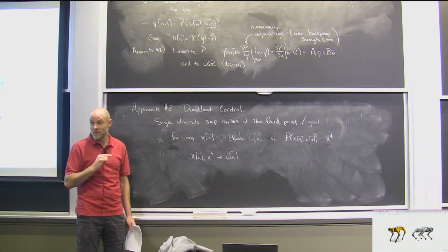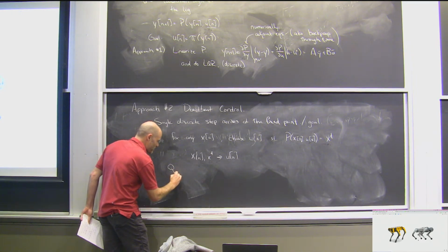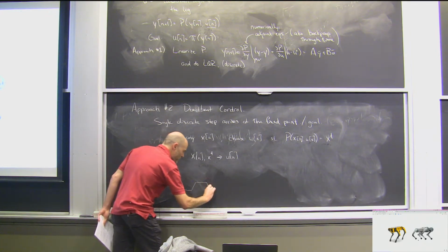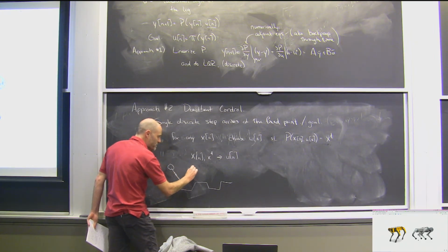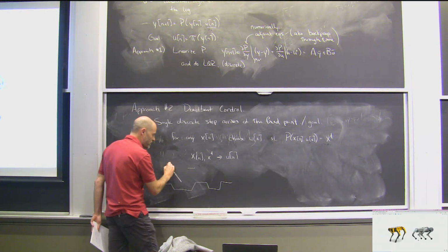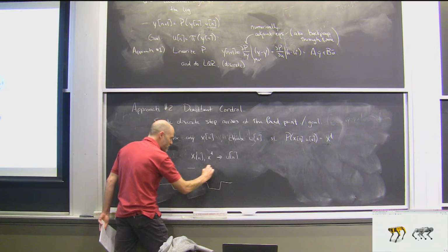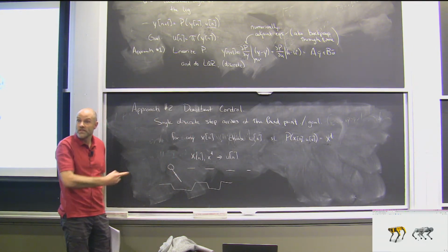Okay, there's a few steps required to get that, but just take a second to appreciate this. This is saying that if I'm in my current hopper, I'm going to run on rough terrain here. I want to achieve that every hop comes back to the same apex, or equivalently, the same running speed. I want to say, no matter where the ground is, I'm going to bounce, and I want to come back up to exactly the same height every time, or to the same speed, right?